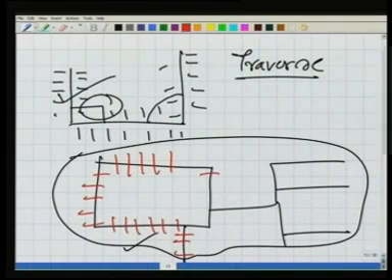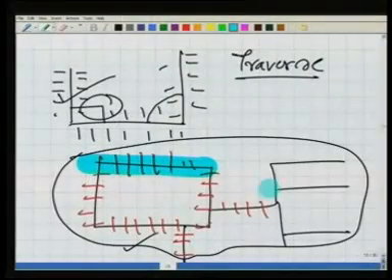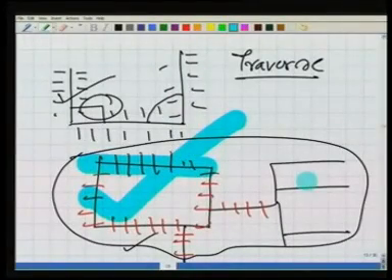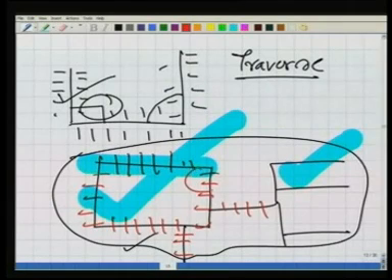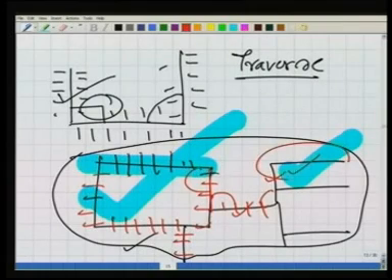So working from whole to part, and this skeleton or the traverse helps us to put these lines together in relation to each other, because there in the field there is a relationship between this line and this line, a geometric relationship. The moment we have carried out the measurements of all the angles here and these lengths, all these lengths and angles, so this line and this line in our map also, they are geometrically related the way they are related in the ground. So this is a really important thing about the traverse. Now we will see the types of the traverse.